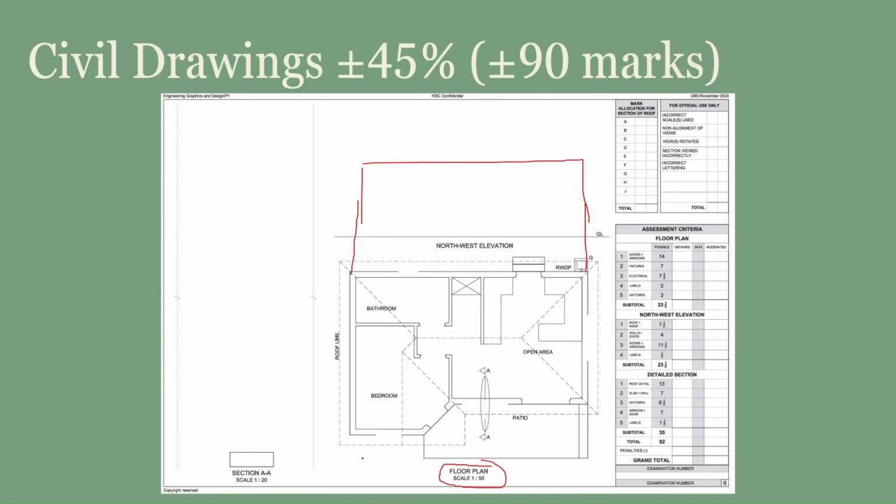So for instance, it's most likely that you will need to draw this view of the floor plan in the elevation. So you will project this window up, that sliding door and this door up, and also the corners of the walls you will project up to the elevation to get the accurate drawing.